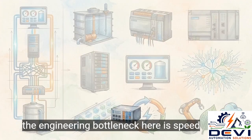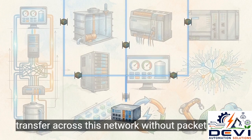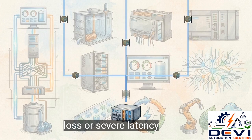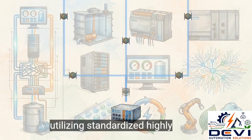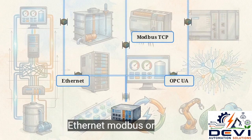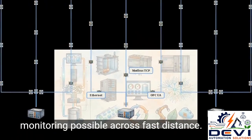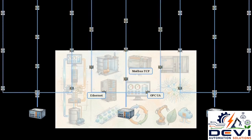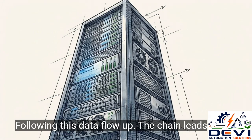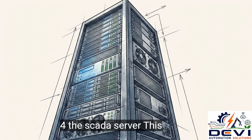The engineering bottleneck here is speed and reliability. Data must transfer across this network without packet loss or severe latency. Utilizing standardized, highly reliable industrial protocols like Ethernet, Modbus, or OPC UA is what makes real-time monitoring possible across vast distances. Following this data flow up the chain leads us to its final destination, Layer 4, the SCADA server.